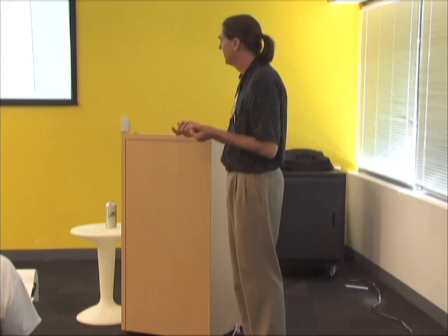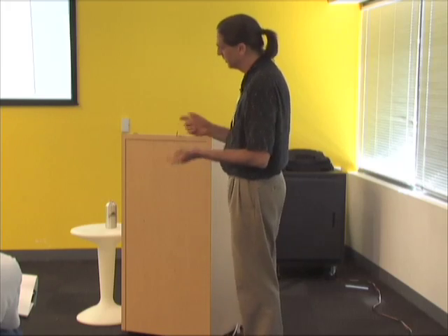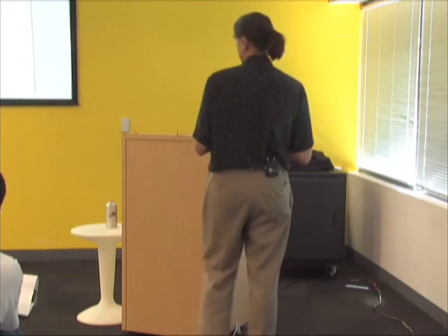Okay, Outliner. I think it's a really good tool. You can find any named group or component in your model easily and zoom to it. I'll show you that in a second. You can change the visibility on any group or layer. You can hide it, you can't change the layer, but you can hide it or unlock it. You can figure out where some element is within your model, if you put a new element into the wrong thing, like a demo layer or demo group. It's a very powerful tool in that way. If you use instance names carefully, as this young man asked me a minute ago, you can absolutely use it instead of doing layers. But it takes a lot of discipline to do that.